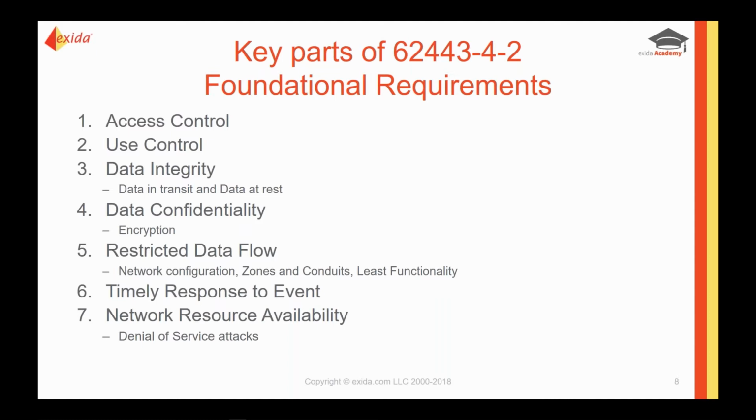Restricted data flow deals with network segmentation. There's a part of the standard 3-2, which you may have seen in the overview. We won't be talking about that too much today, but that's entitled Zones and Conduits. And what that does is provide guidance on establishing areas within your system of higher security and lower security.